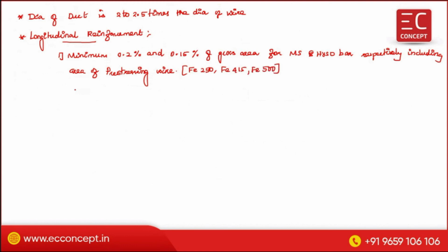Okay. Second point is for depth more than 500 mm, 0.1 percent of gross web area is provided as side reinforcement.